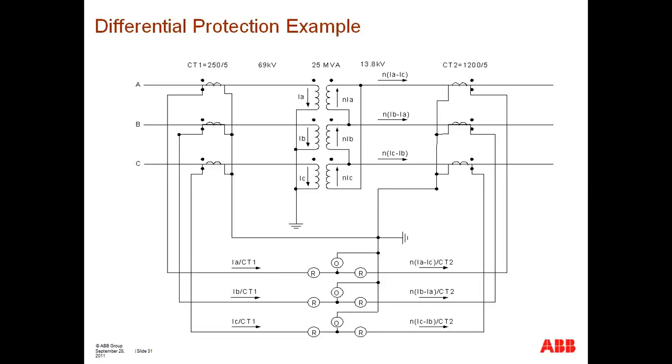I'm going to assume that what the question is, is that when monitoring a transformer that has no phase shift at all from one winding onto the other winding, you should expect a 180 degree relationship between the high side currents versus the low side currents, and this is because of the way the CT polarities are installed. I'll explain that in just one second with the slide that you have in front of you.